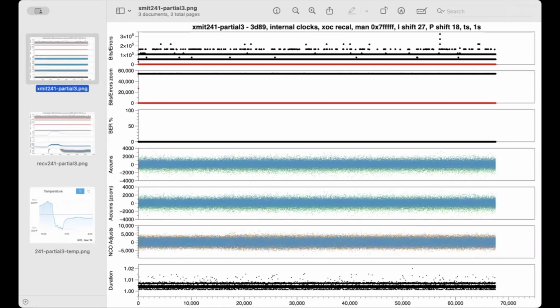Now, above that, you see several different lines of black and some scattered points. This is a known problem. We talked about this last week. We think this is due to clock domain synchronization, and Matthew is working on a fix for that. You can see the bottom black line is the real one. That one's actually pretty solid. If you zoom in, all the other lines are broken up. They're just individual points. Sometimes it just skips reinitialization because of this clock synchronization problem.